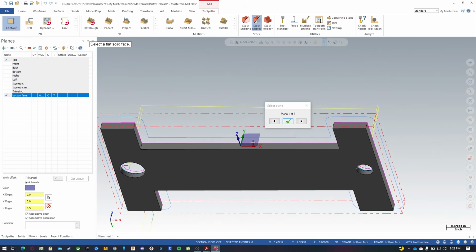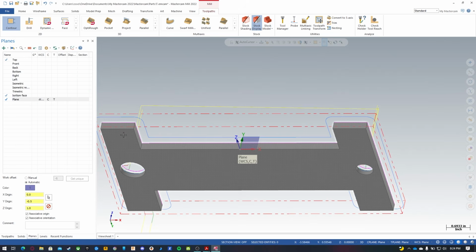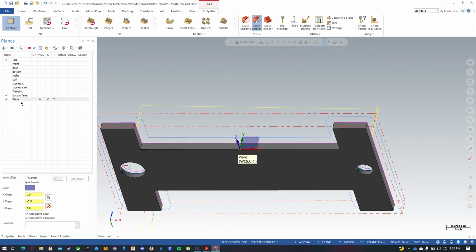I'm okay with this gnomon the way it is, so then we set up off the center, or what we can do is move that. We can shift it back, so we just use an edge finder right off of this face. So if we just click OK, and we can move it in the Y, or the Z here, we can make it 0.5. And if we tap enter, it shifts it down. So we can edge find that corner. So if we click OK, and we use this plane, this will be corner side 1.